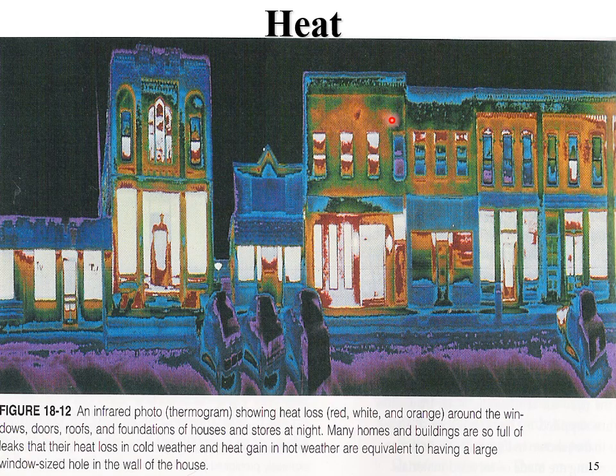So the possible reasons can be that, A, this is a separate room and the windows are open and the whole room is super cold. But a more likely scenario is that they have a thick curtain that's been drawn, so that's helping keep the window surface cold, closer to the outside temperature, while keeping the heat inside. Okay, so that's another thing you can look at because of an infrared photo or a thermogram.